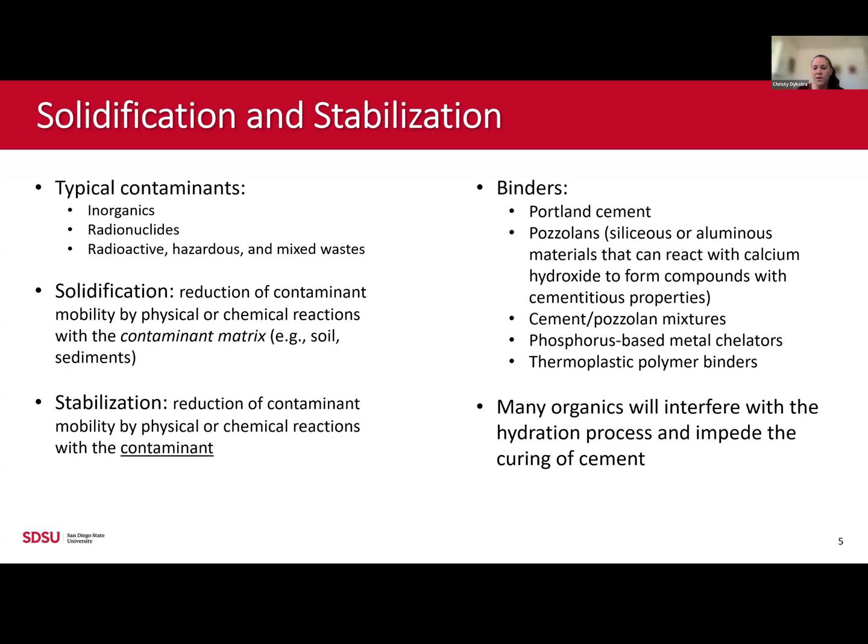And so things like, let's say, a cement, where we are putting that solidification material into the soil, that is going to react with some of the soil around it. It's going to create like an encased area, and we're going to prevent the mobilization of that contaminant.